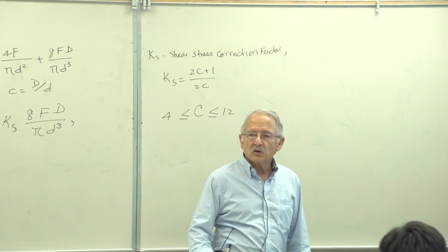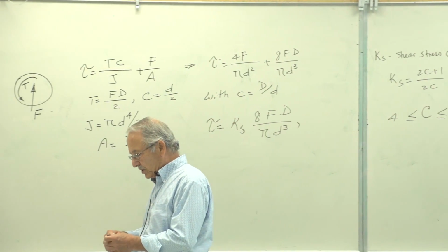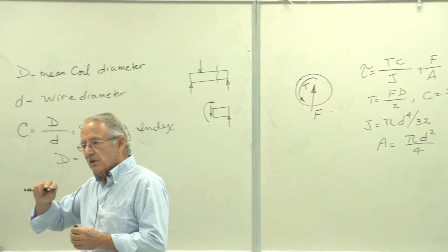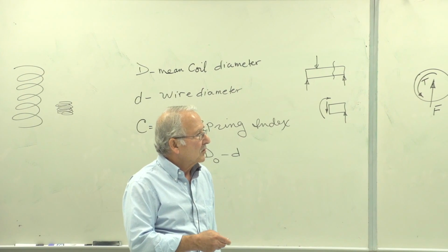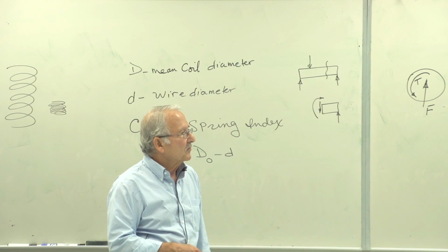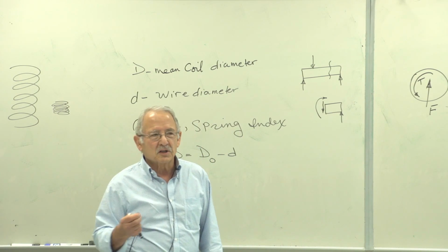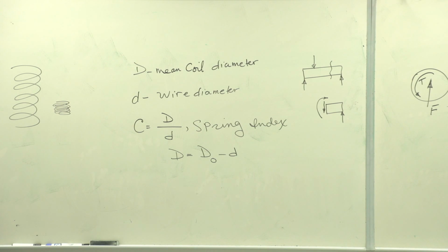And similar to all curvatures that we have seen so far, these curvatures produce larger stresses where the radius of curvature is small, inside of this. And we've used stress concentration factors to represent this. Remember the fatigue problem with the leaf spring and bending?